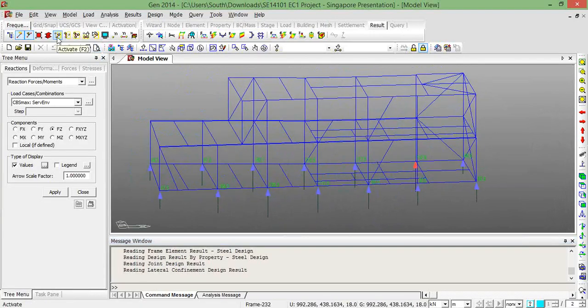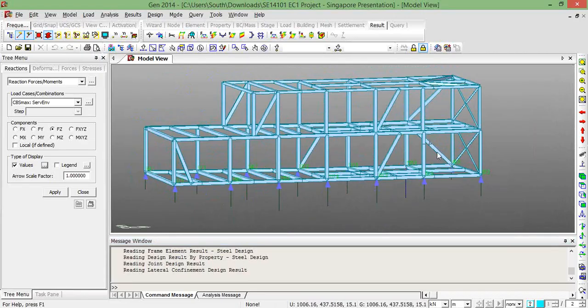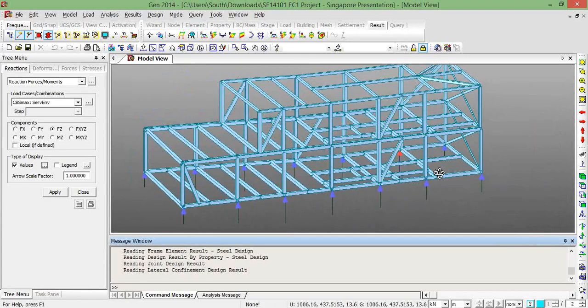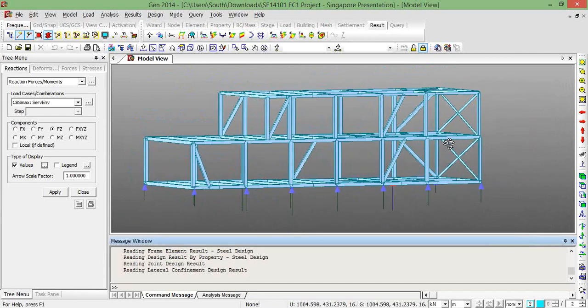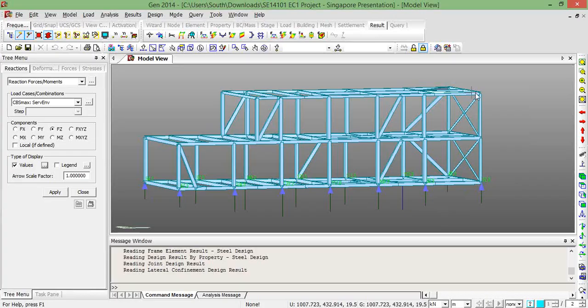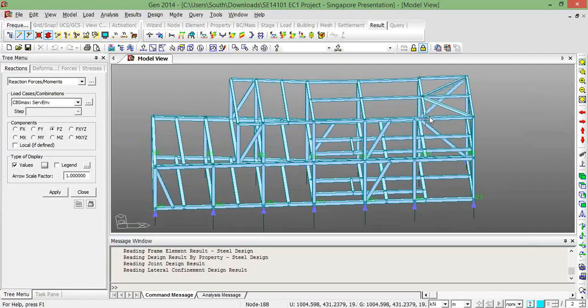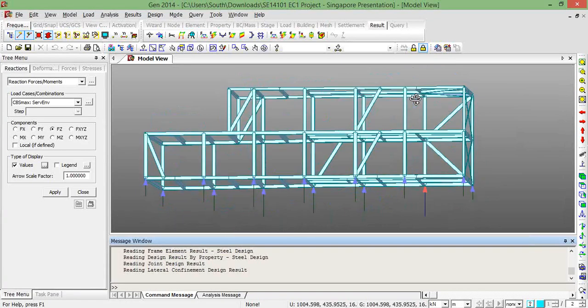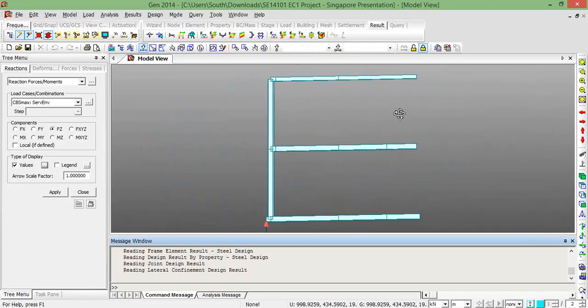One thing we had to bear in mind is that in the existing building, they had large glazing here where the staircase comes up, and a part of one of the conditions set by the local authority was for that to be continued into these additional 2 stories. So one of our frames could not be complete, so we've got a half frame here. We'll just highlight that. This is our half frame.